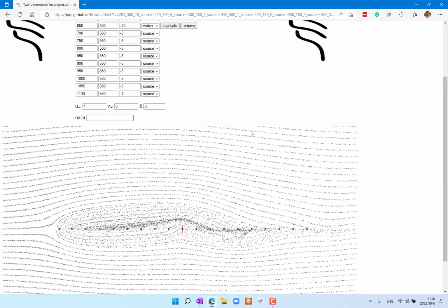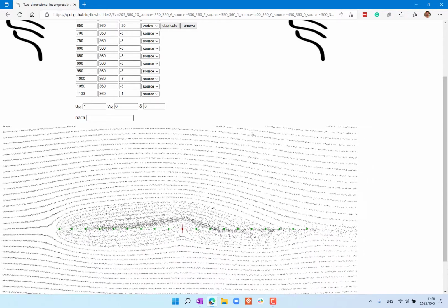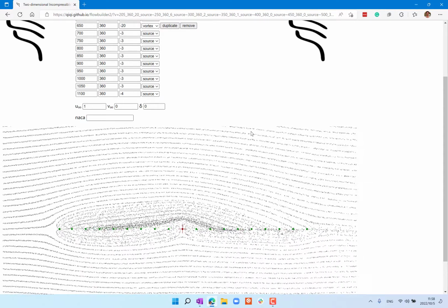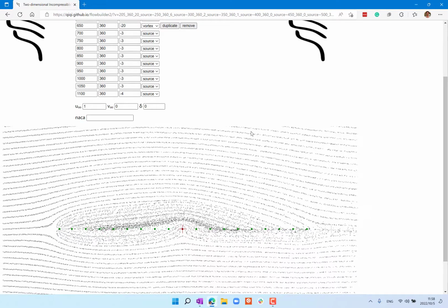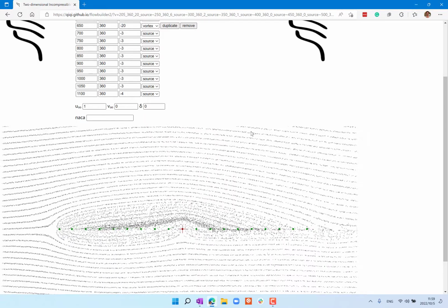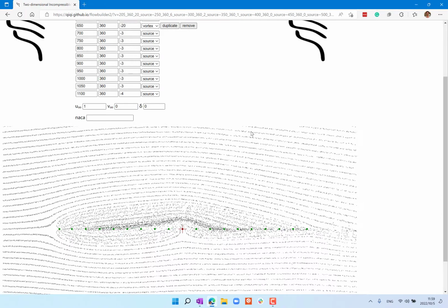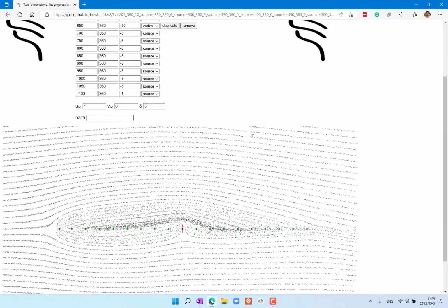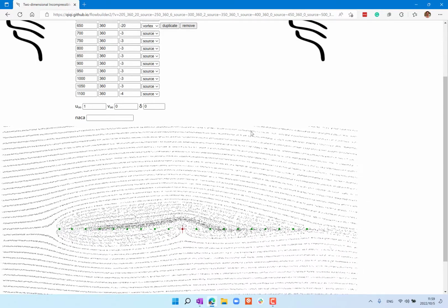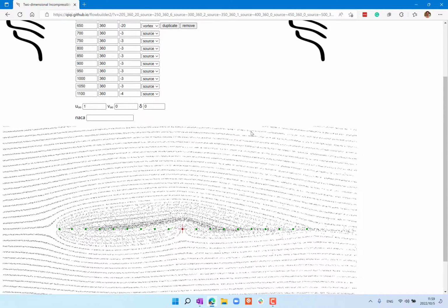And you're going to see that I am going to be creating a cambered airfoil over here. So this now starts to have a camber, but it's totally not obvious what the camber is, right? We know that by placing a vortex here, the camber is sloping upwards upstream of that vortex. It's sloping downwards downstream of that vortex, right? But if you want a particular camber, it's a little bit hard to place the strength of the vortices to get that camber.